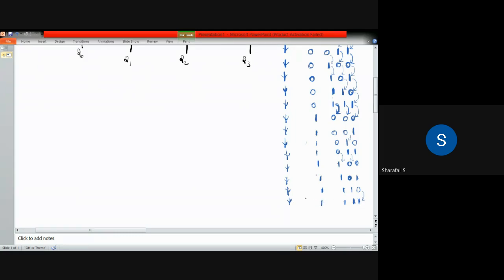So these are the values. And if you consider the next clock pulse, what will happen? Q0 will change from 1 to 0. So 1 to 0 means it is at the negative edge of the Q0 value. Since it is at the negative edge, and that is given to the second flip flop, this one also will be toggled to 0, for flip flop 2.